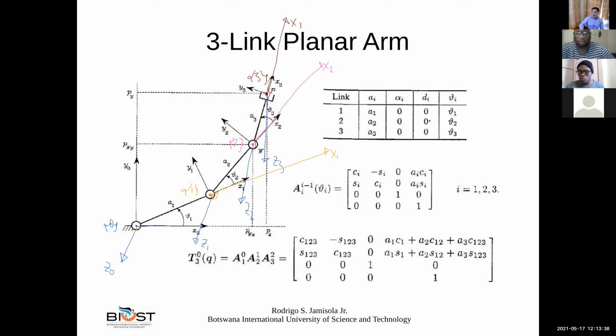So now we need to derive the DH parameters. Okay, that is alpha i, a i, d i, and theta i. Now, because in this case theta i is the variable, we don't know what exactly this angle is. We can put 30 degrees probably, but it is easier to just say theta 1, theta 2 and theta 3. Okay, easy. How? Well, theta moves from here, from Z0.